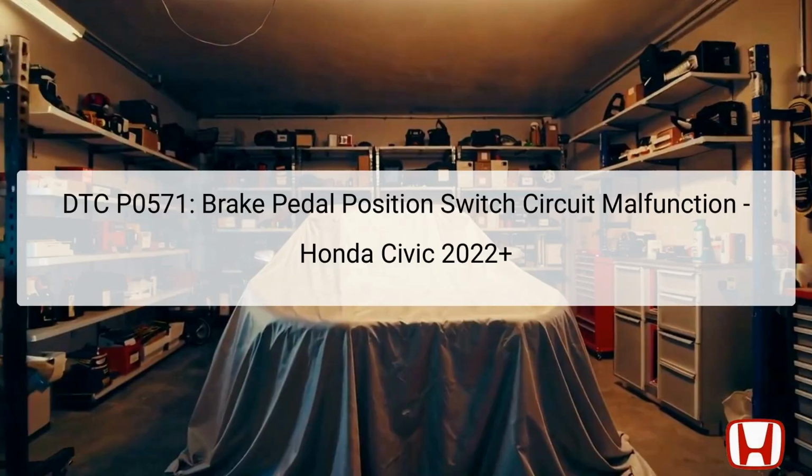The diagnostic trouble code DTC P0571 indicates a malfunction in the brake pedal position switch circuit on the Honda Civic 2022 and newer models. This code is triggered when the powertrain control module, PCM, detects an inconsistency between the brake pedal position signal and the actual operation of the brake pedal.